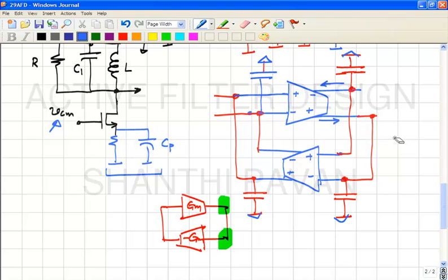Okay. Now, please note that when I draw this animal here, what does it imply? Internally, what is there? There's the differential pair which is converting the input differential voltage into a differential current, and there are those PMOS current sources, and there is the common mode feedback loop which is sensing the common mode output and tweaking the gate of the PMOS transistor such that the output common mode is held to VCM ref. Okay, all that is implied when I draw that trapezium with two input voltages and two output currents. That clear?